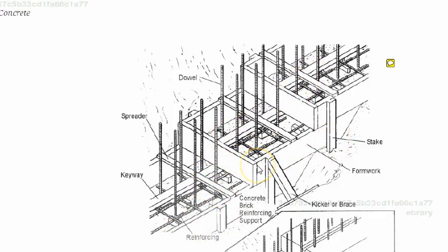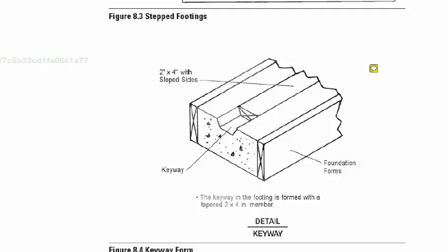and catastrophic failure happens if the board comes loose or you didn't put enough nails in it, it pops. Concrete starts moving all over the place. You not only lose the work, it can kill or injure a worker, your finishers, or your crew, and we don't want that. Above all, you always want to do things safely.